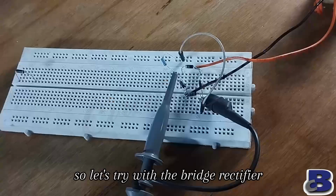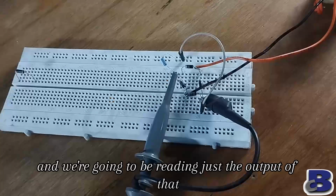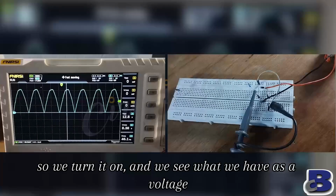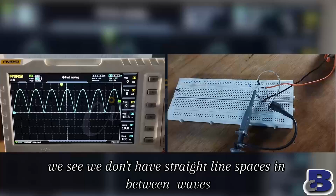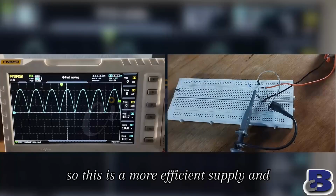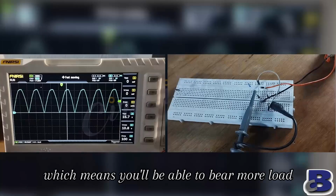So let's try with the bridge rectifier. So we have our bridge rectifier connected, and we're going to be reading just the output of that. So we turn it on, and we see what we have as a voltage. We see we don't have straight line spaces in between waves. So this is a more efficient supply, and this will definitely produce more power compared to the half-wave kind, which means you'll be able to bear more load.